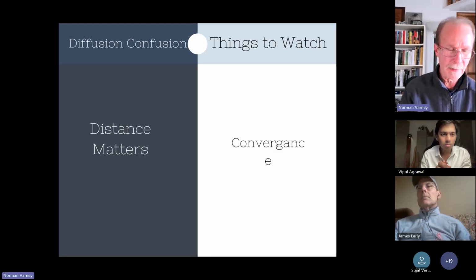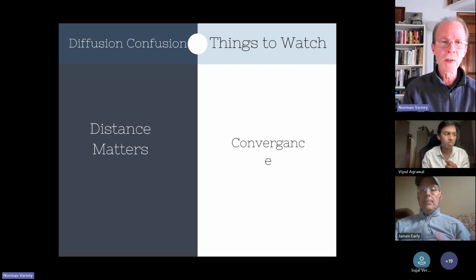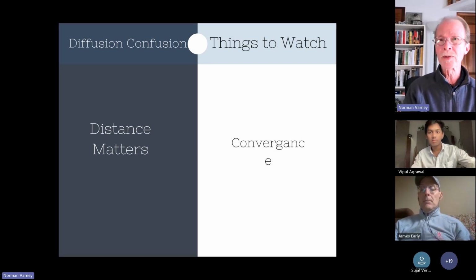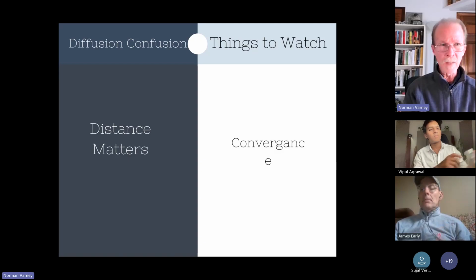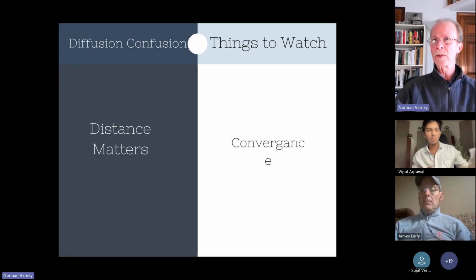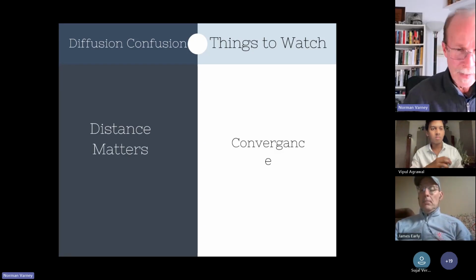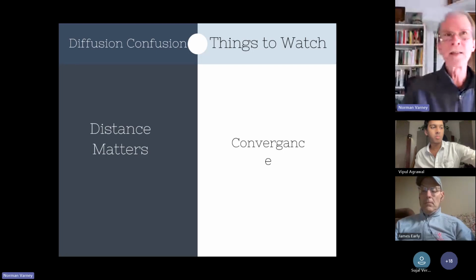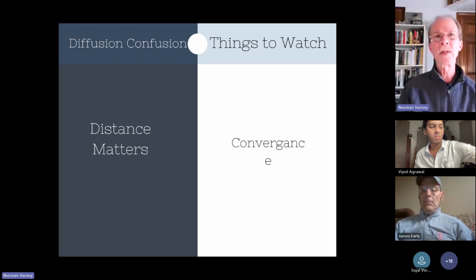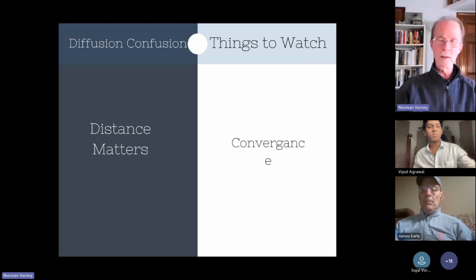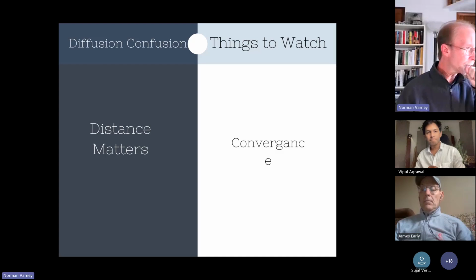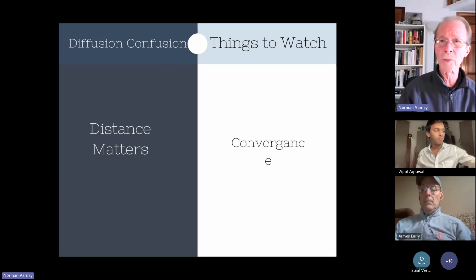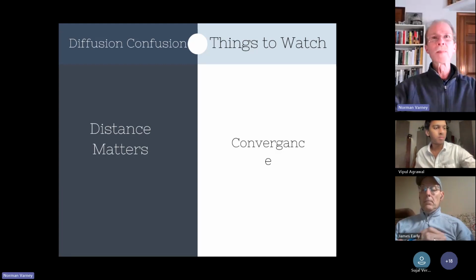No, this is easy. The first thing we would want to know is what the reverberation times in the room are. And secondly, are the first order reflection points controlled? The existing reverberation times are going to dictate how we address those first order reflections. We can put absorbers there.